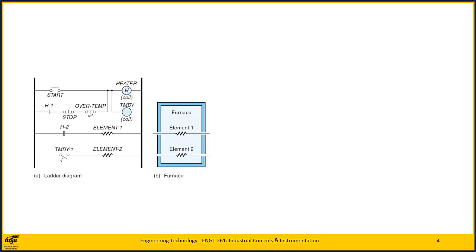There is an important fundamental difference between a relay logic ladder diagram and a PLC ladder diagram. The relay ladder diagram is basically a wiring diagram, and a rung becomes active when current can flow from one power rail to the other. That is, if there is a path for the current through the contacts, then the load will be energized.